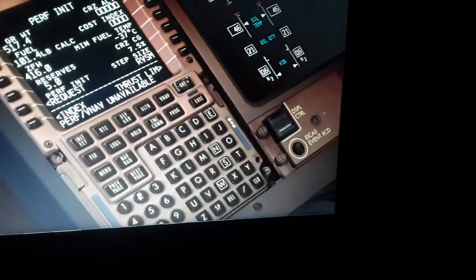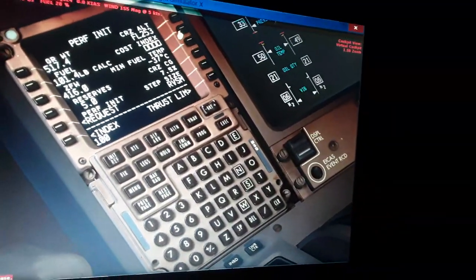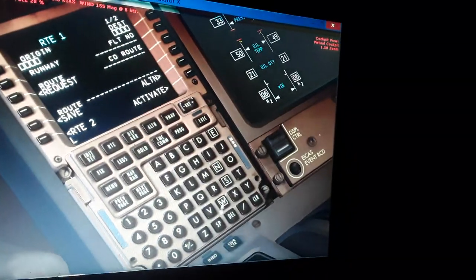So one last step left before takeoff. We need to set up the flight management computer like this. So we have the latest menu, as you can see, the model position initialize, LSZH, the reference airport, the route, zero fuel weight, gross weight, reserves 5%. So this is going to be the calculations for takeoff. 25,300 feet, the takeoff altitude like this, the cost index, the minimum fuel temperature, and the center of gravity for